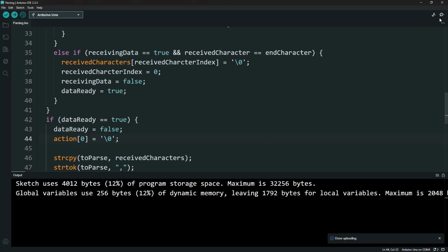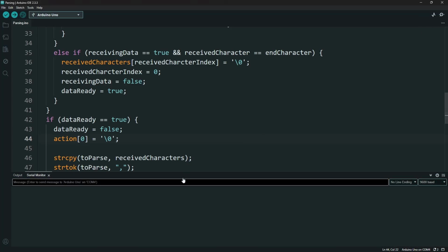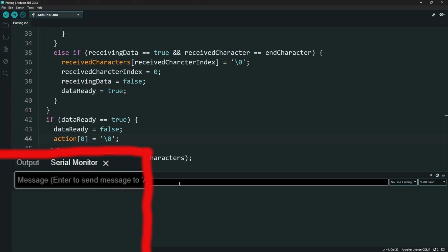No, everything looks good. Okay, so I'm just going to go to the serial monitor now, and we're just going to test out the code. So what I'm going to do is I'll do a get, and I'll just get the current pin state of pin 3, which is 0 at the moment, and I'll now set pin 3 to equal true or high or 1, whatever, and now I'll get pin 3 again, and yeah, so now we get a 1 back.